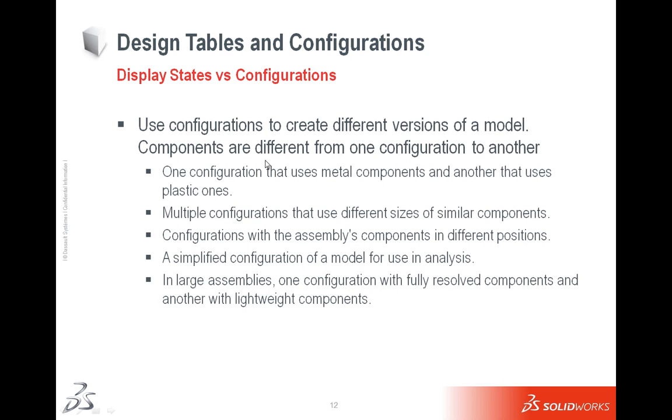For configurations, as we've been talking about, this is when you're changing the various sizes, simplifying parts, components that use different dimensional parameters or material parameters. Those are the reasons why you would use configurations.